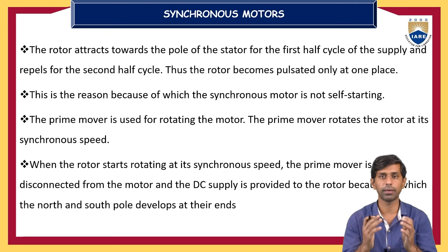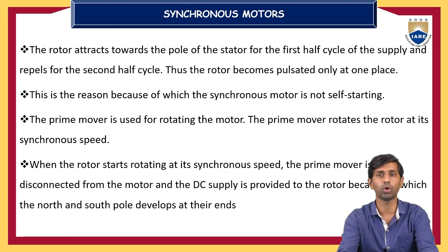For example, when we are going to use one prime mover, whether it is a DC motor or an induction motor, it is not an issue. So let us consider one prime mover. It is connected to the rotor of the synchronous motor, as an auxiliary prime mover. This prime mover will start the synchronous motor, running at a speed nearly closest to the synchronous speed. So once the speed of the synchronous motor attains close to synchronism, that is, close to the rated speed,